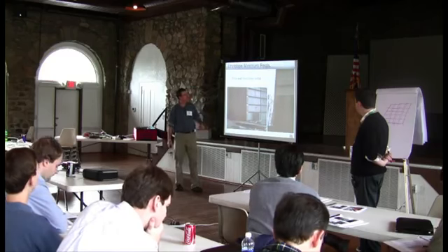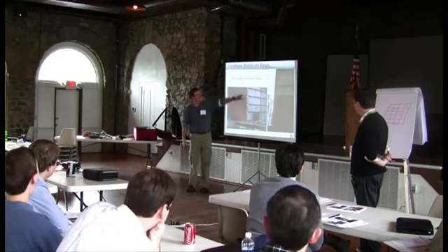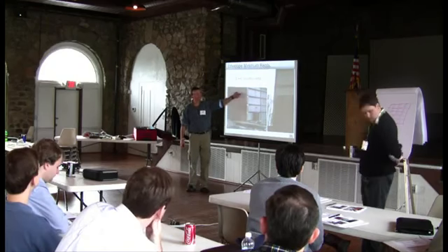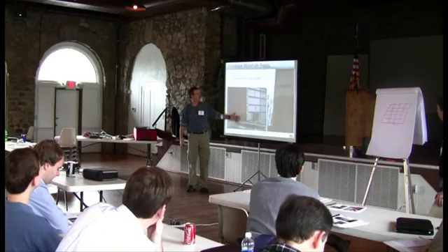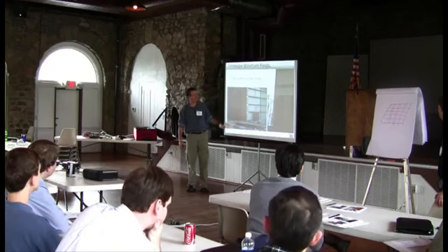So here they're doing vertical insulation, and they are compressing it, but only at the purlins. And I think this is actually a decent assembly right here, with the metal, in essence, cladding. That's our metal cladding. We do have to be careful about air sealing and things like that, but this can work.